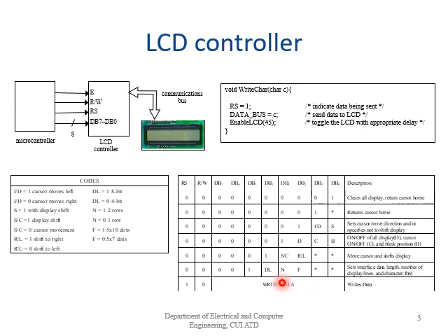Here you can see in this example the code. This is our void function write character. The character comes in, we set RS to 1, and the character will be written on the data bus, that is DB0 to DB7.